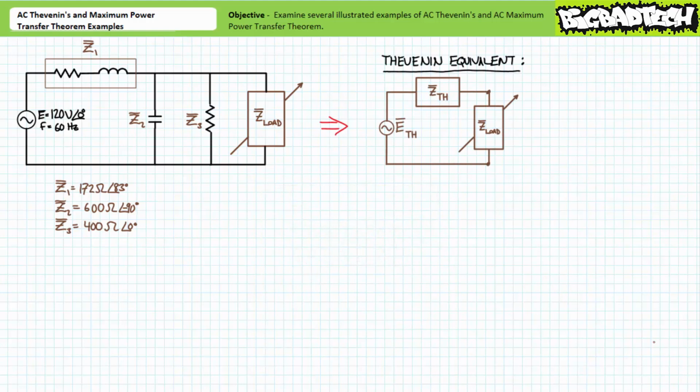If you've been following this playlist in its intended sequence, you are no doubt aware that Thevenin's theorem is a procedure that simplifies a complicated series parallel circuit into an equivalent simple series circuit. The original and the Thevenin's equivalent should ideally behave the same, and importantly, the variable load impedance should be none the wiser to the substitution. Of note is not only the substantial ease with which calculations can be made using the simple Thevenin's equivalent circuit, but also how much less components, connections, and confusion is involved in the physical construction of the Thevenin's equivalent circuit.